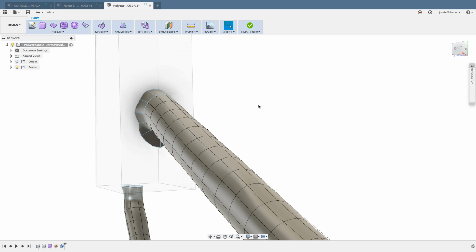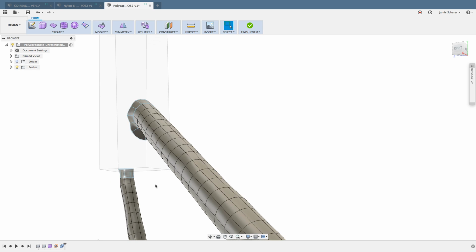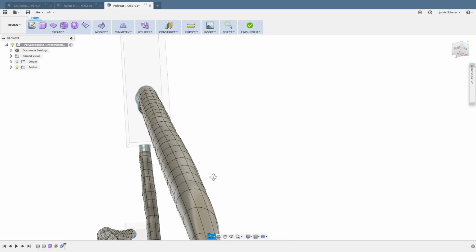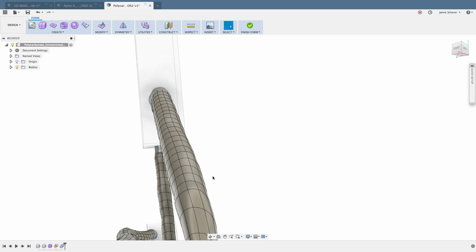And the reason it's doing that is because if we start to pull these edges off of the solid, then we'll have a hard time automatically turning this back into a solid when we're done. Now, we could unfreeze that. We might want to make changes or change that shape. Not a problem. We can unfreeze it later. But just know that anywhere the T-spline geometry touches up against a solid preserve, the edges are going to be frozen. The next thing that I'll talk a bit about is some better ways to work with this geometry.